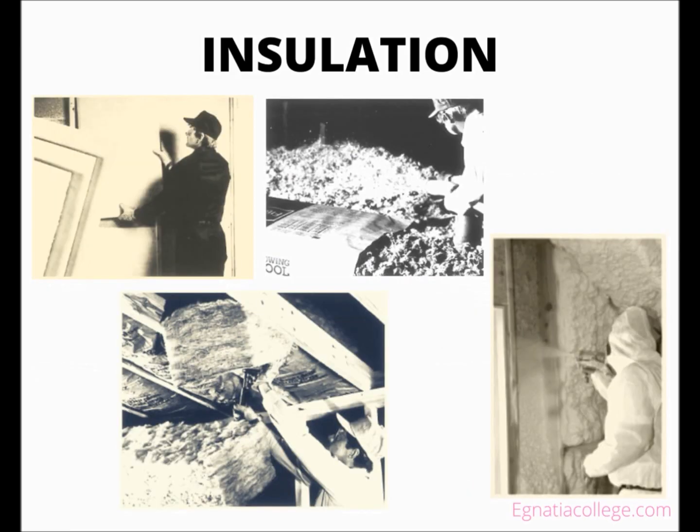Thermal insulation is generally available in 4 forms. Foamed in-place materials are synthetic compounds that are sprayed onto a surface and that then produce an insulating foam by a chemical reaction. Rigid boards are plastic foams that have been produced in board form at a factory. Another common type of rigid insulation is made of fiberglass that is manufactured in rigid form instead of as flexible blankets. Rigid boards are frequently used for foundation insulation, under concrete slabs, and for sheathing.